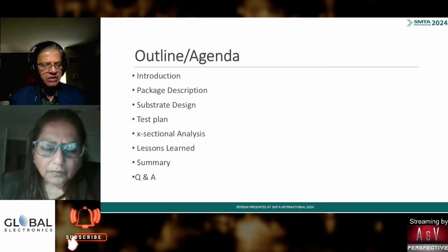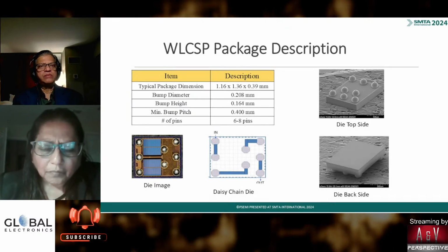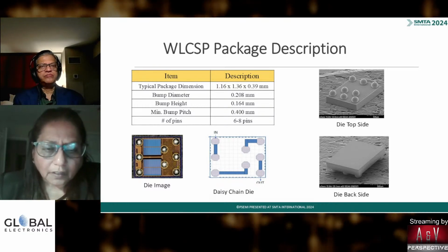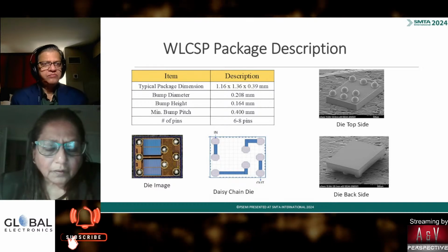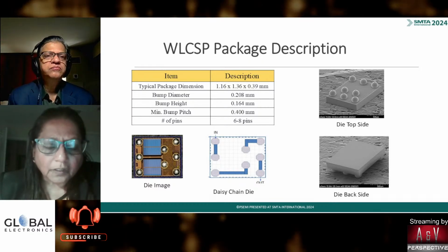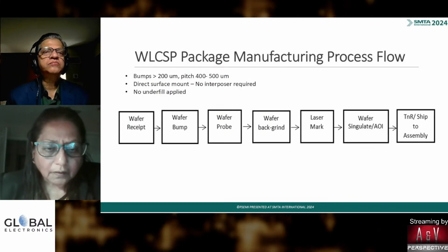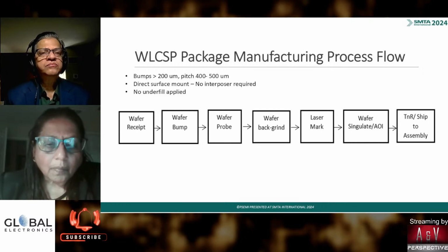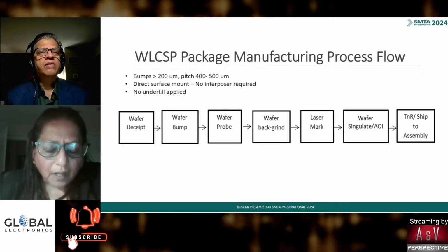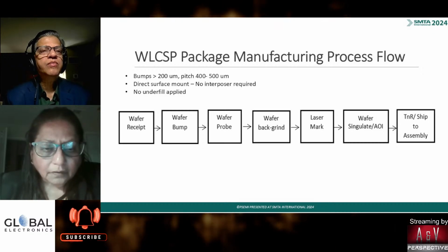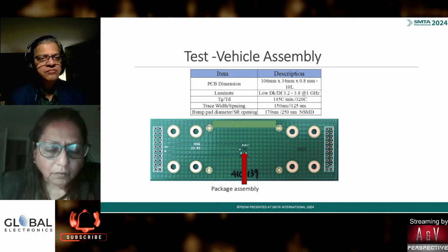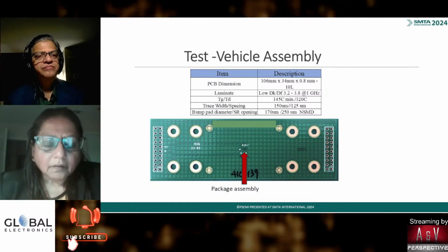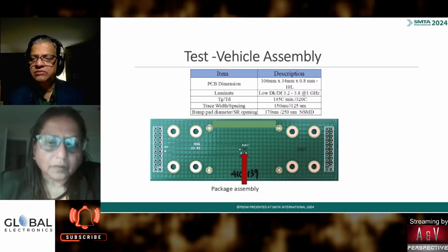If you just take a component and test it for the JEDEC standards for thermal cycling, temperature humidity, high temperature storage, you have tested it without putting it through a heat cycle. By soldering it on the board and then testing it, you have put it through some more heat impact, and then see how well that survives.